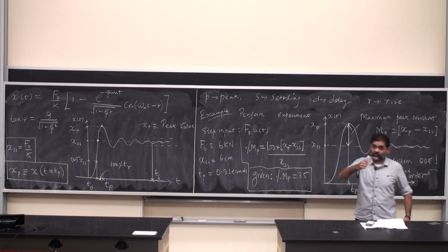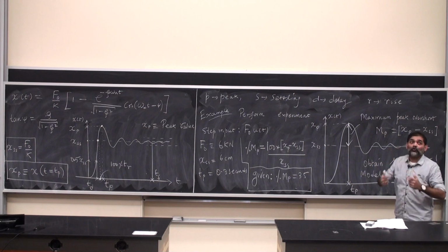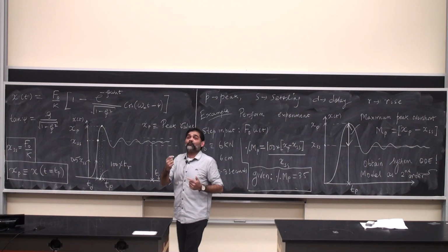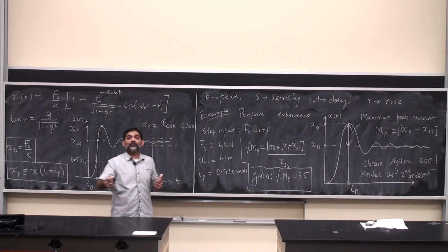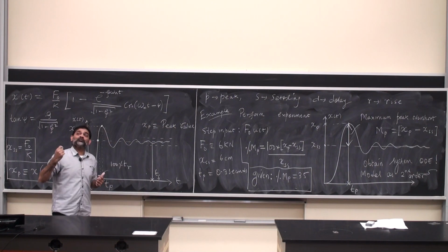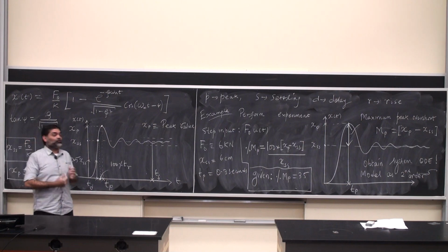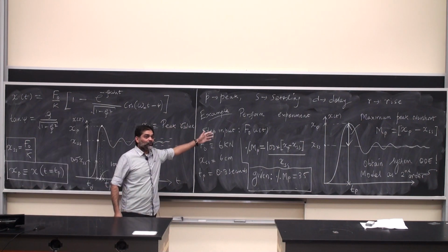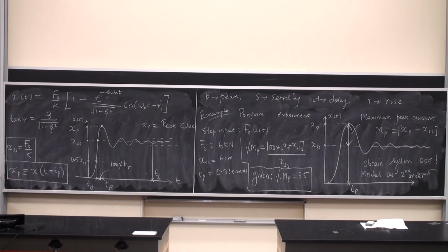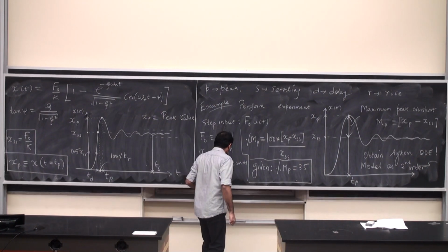Absolutely. So you're close. The right answer is I cannot model it as a first order system because we know that if I have a step input to a first order system, it is just going to show an exponential behavior. If I have a sinusoidal input to a first order system, it will show oscillatory behavior. But the input here is a step input. So the only system that adheres to this particular command is a second order system. That's why we modeled this as a second order system. Alright. Good stuff.